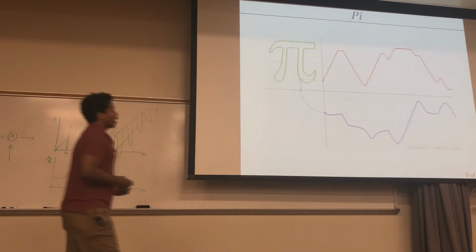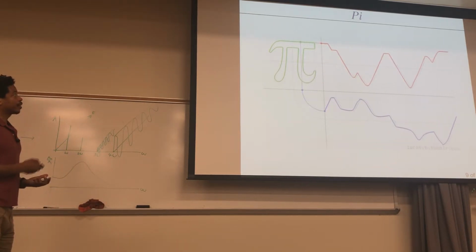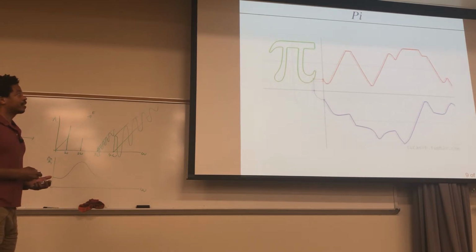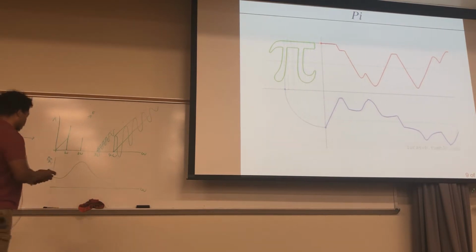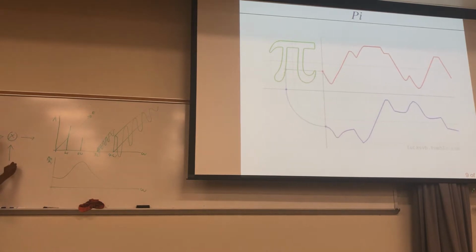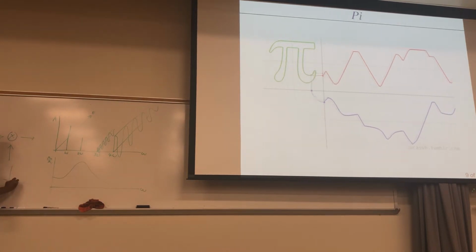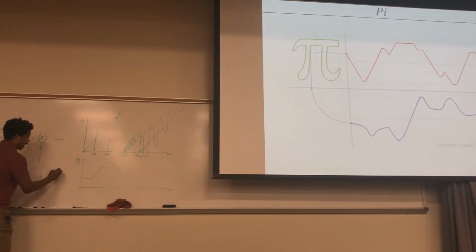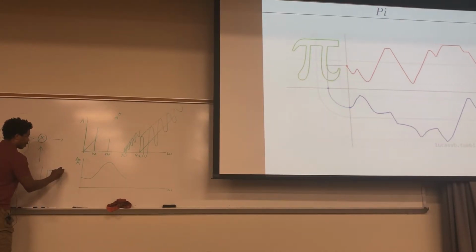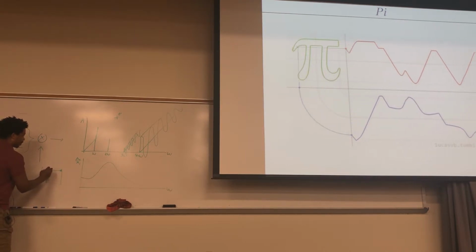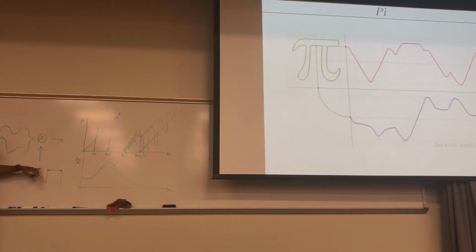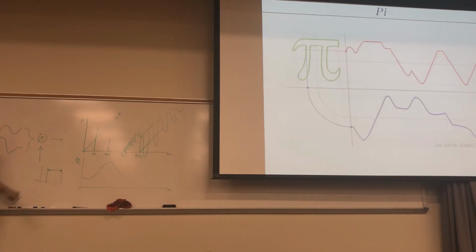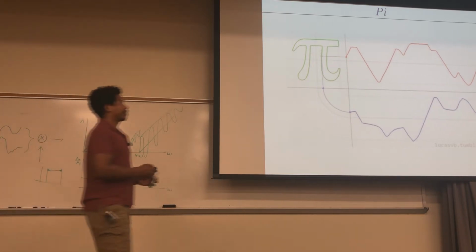Fourier series can be used to make just about any kind of signal. Really sharp corners are really hard to make with Fourier because you get the Gibbs phenomenon. So if you're trying to make a really nice, perfect square wave, you're never really going to get it, because you have these little peaks that pop up at the ends by the Gibbs phenomenon, and there's a minimum value that it gains, but there is a limit. But otherwise, you can make all kinds of other shapes.